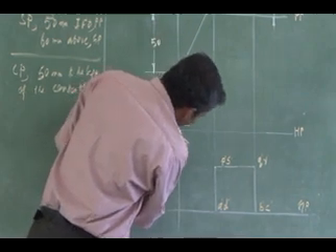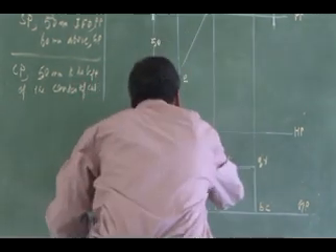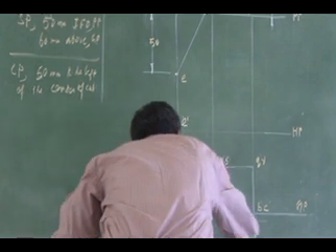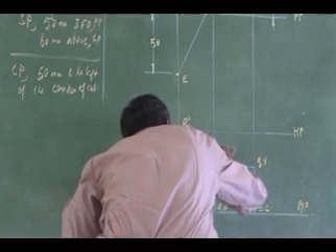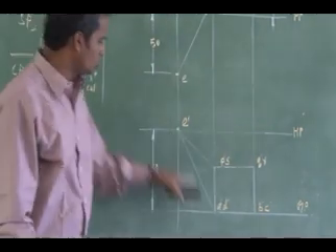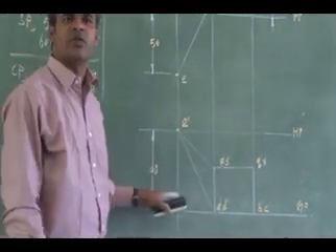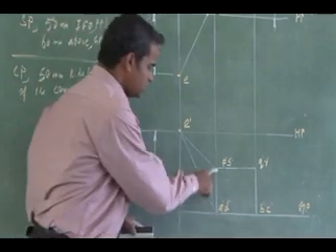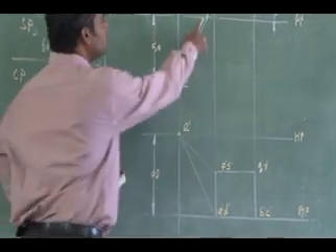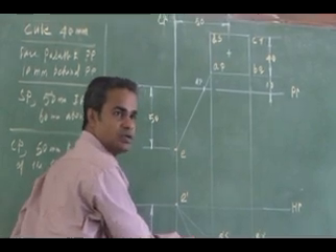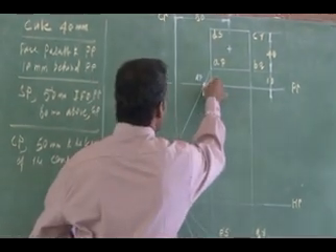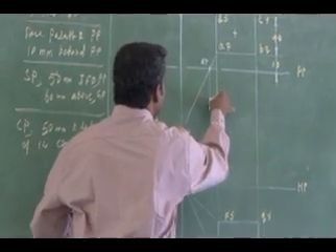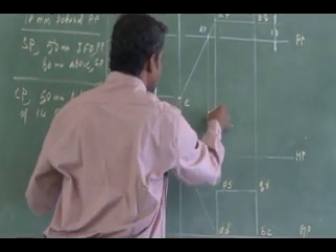So I look at the edge A and P and draw a ray of vision like this. These two lines are the rays of vision in the front view. This is A, this is P. Now if I project this intercept to that ray of vision in the front view, that is the location of my perspective. That's it.